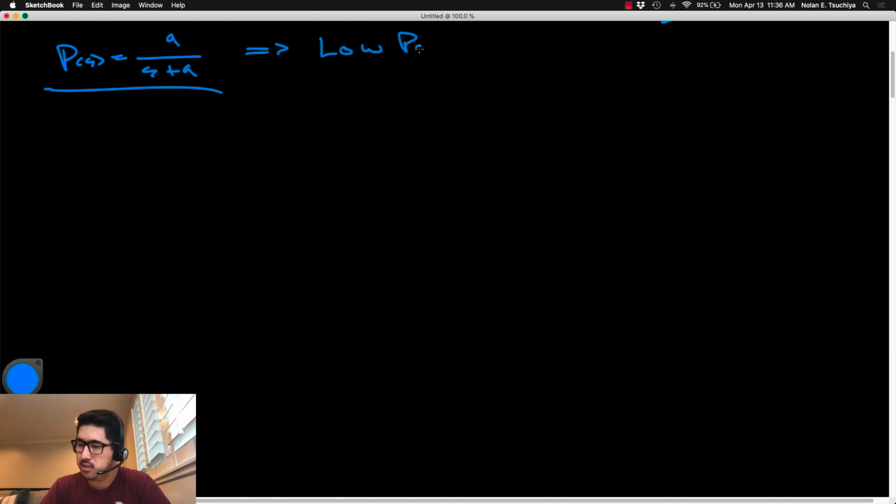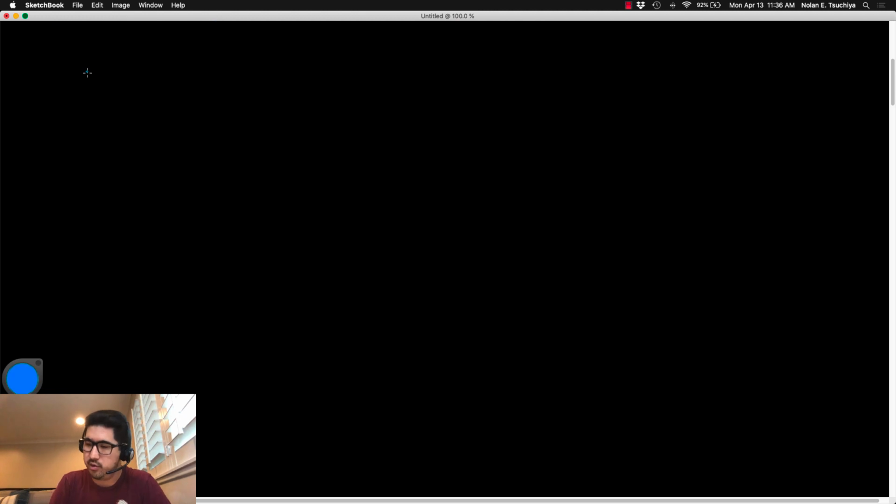One example that we looked at last time was the simple transfer function that has the form of a over s plus a. Okay, so a very simple first order transfer function of this form. It turns out that in general this is called a first order low pass filter. And today in the lecture, we're going to explain what that means and its application to certain engineering fields. Okay, so let's start by drawing out an electrical circuit.